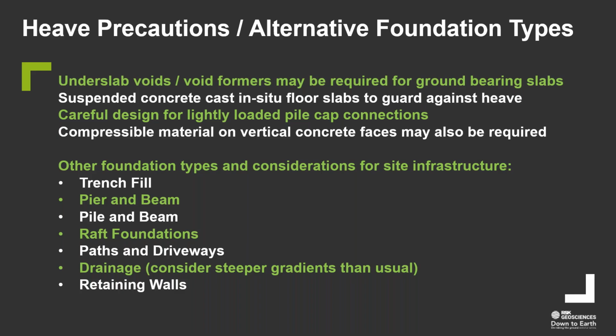It goes without saying that on schemes where we do have trees present, it can get very awkward when designing paths and driveways and trying to protect those so that they stand the test of time, and drainage runs as well, in terms of laying them perhaps to steeper falls than usual.